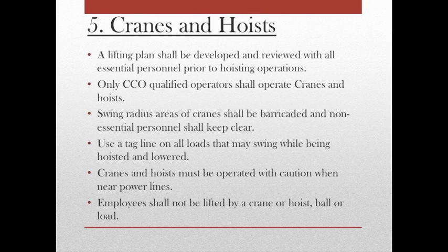Cranes and hoists. A lifting plan shall be developed and reviewed with all essential personnel prior to hoisting operations. Only CCO qualified operators shall operate cranes and hoists. Swing radius areas of cranes shall be barricaded and non-essential personnel shall keep clear. Do not touch the crane or load while it is in motion. Use a tagline on all loads that may swing while being hoisted and lowered. Cranes and hoists must be operated with caution when near power lines. Do not take any equipment within 10 feet of energized lines. If in doubt, consult the safety department and review current regulations.